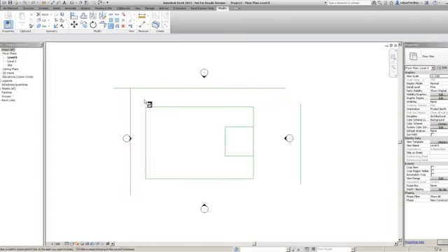So again, I'm going to pick that line and pick that bit. It's not uncommon for you to trim away the bit you want to keep, or sorry, keep the part you wanted to trim away. It's quite common when you first start using it, but you do get used to it, I promise. In this one here, again, I'm going to pick that one just there, and then hover over this line. You see how it's soft selecting to extend it up. So even though it's missing the line, it will extend it up to the plane that it sits in, like that.